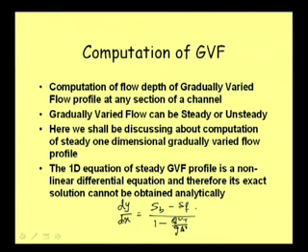This is rather a function of y, because S_F, that is the friction slope, or say the top width, or here the area, all these are basically functions of y. If it is a non-prismatic channel, then only will these things also be varying with x. If it is a prismatic channel, all these are pure functions of y.